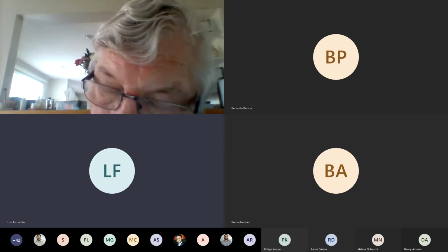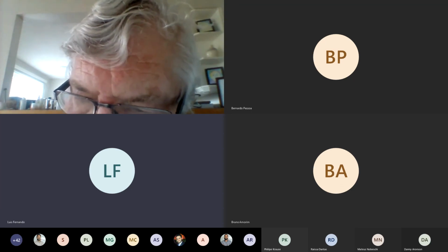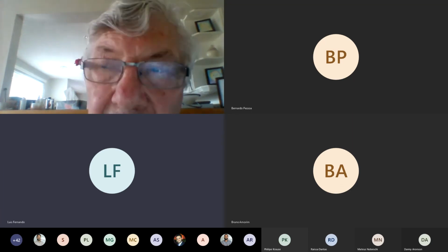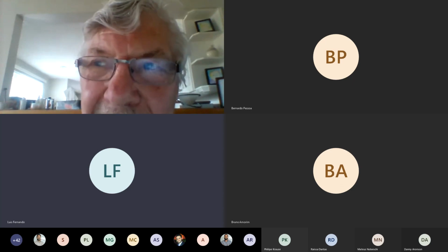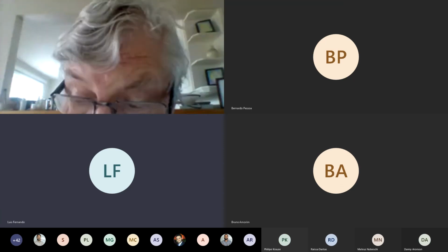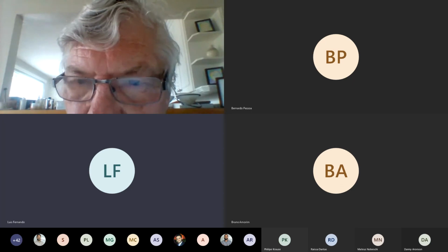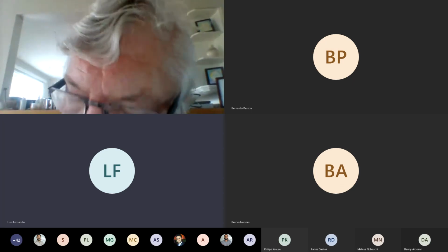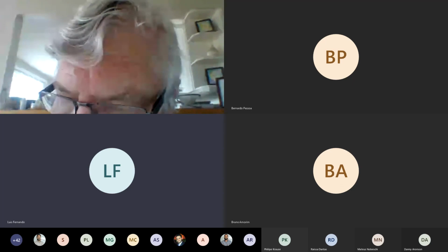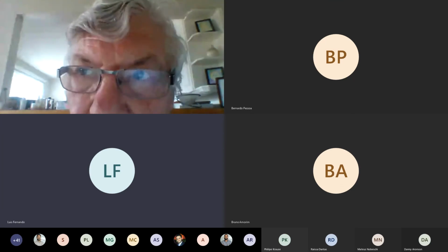The second thing that they've done quite a bit of research on, at Nova or TransCanada, is how a shark, if you look at a shark's skin, it has what are riblets. Riblets. And we've only done that in small sections to see if it would work. But Kamal Bartras did a lot of work using riblets, and that has a lot of potential. It's creating small undulations on the inside of the pipe. So you have to find out how you can do it on a small pipe, and how to do it extensively on a pipe. That would be the future, to reduce the friction losses both on the gas pipeline and liquids pipeline. So riblets. Yeah, riblets. Right. Yeah, I see.